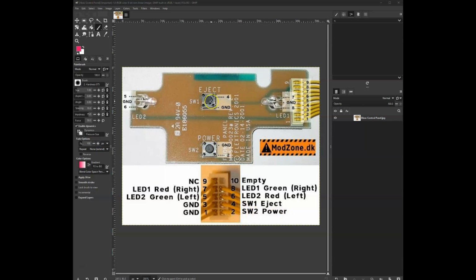Your main connections there. Anyway, on to what I actually did with the board with the LED lights. I had to remove them. I tried to utilize them, but I plugged them in and wired them sequentially to the HDD or the LED. I used both slots on the motherboard, those pinouts, and for some reason every time I booted it up, once I got to BIOS, it would just restart, rinse and repeat, and stay in this restart state.